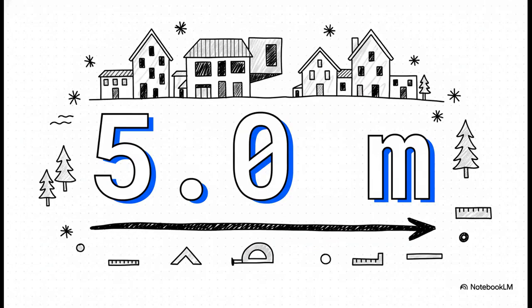This is it. This is the number, 5.0 meters. It's the magic number, the line in the sand. It is the one thing that decides if your cantilevered spaces count against your buildable area. If you're designing in Norway, you have to burn this number into your brain.